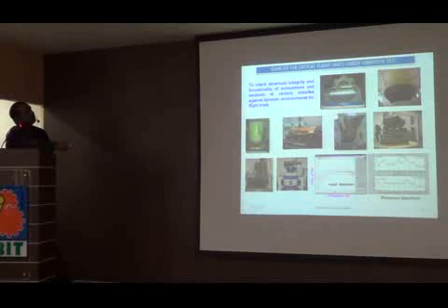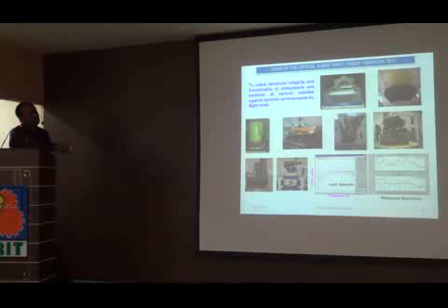What we do basically in all of this, like I have told you, is we input at the base of the system some kind of spectrum like this, what we call a random vibration spectrum, where the y-axis is in terms of G square per Hz and the x-axis is frequency. It is similar to G versus frequency. Because it is random, we need to give it in consistent units called G square per Hz. This is what we call power spectral density.